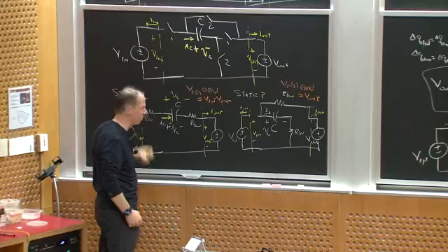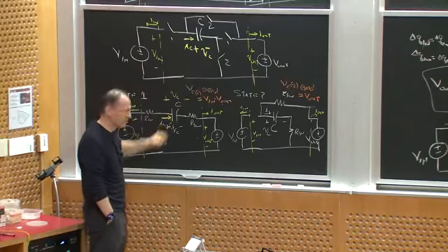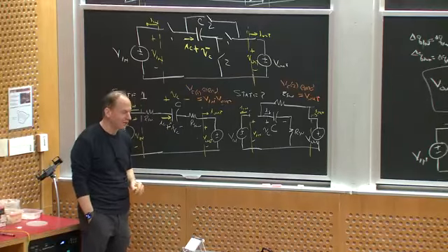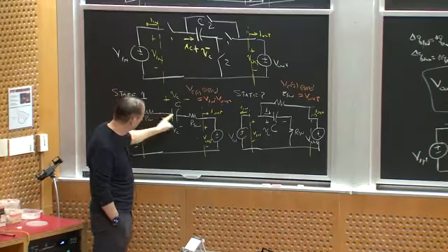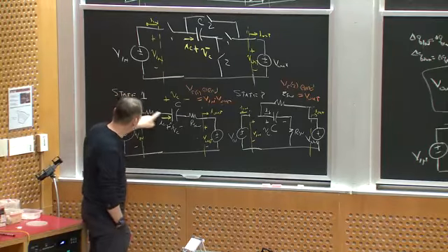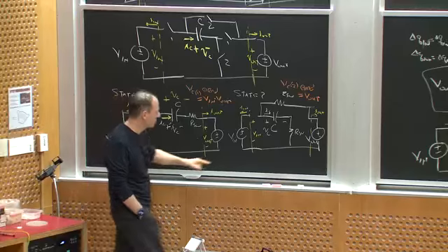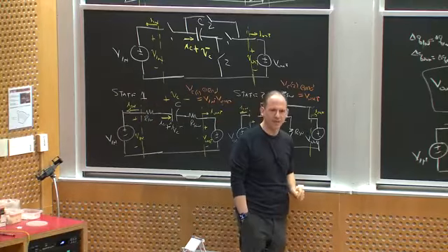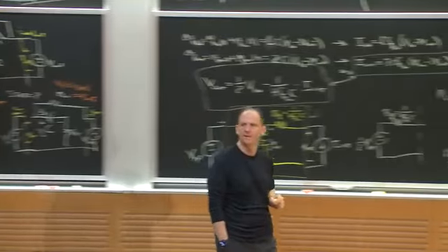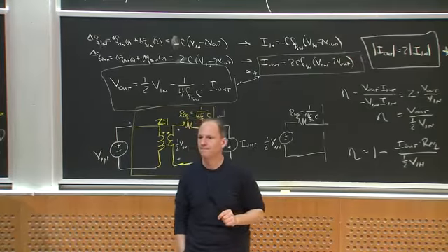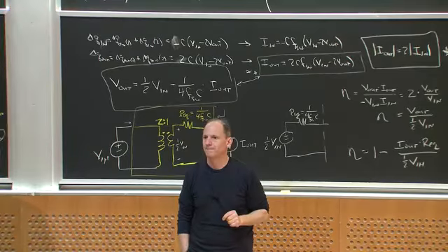The actual value of the resistance doesn't matter. It doesn't even matter if the resistance is linear or nonlinear, but you get the same net loss. So it's basically the loss that I incur in putting the charge on the capacitor and then taking the charge back off the capacitor to the output. That's the loss that's included. Yeah. So if you use a smaller capacitor, which takes less time to charge and discharge, can you see smaller losses?